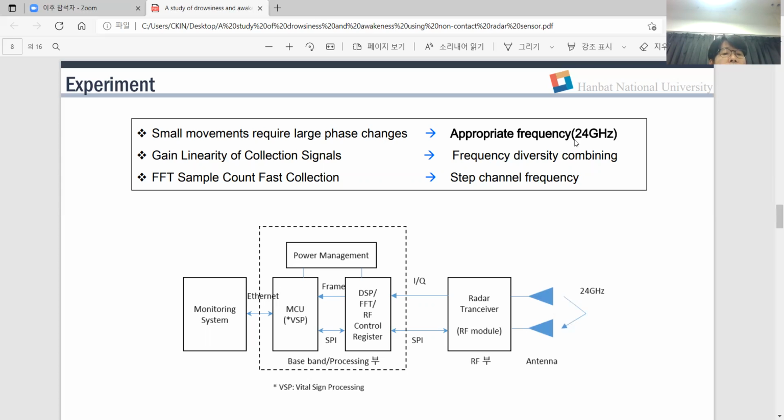However, since the human heart rate contains human body specificity and does not have complete periodicity, depending on the characteristics and conditions, there is a limitation in representing it as a single peak. Biosignal variation information, that is, variability with time, is an indicator according to the activation of the sympathetic and parasympathetic nervous system, and contains more human body information than the heart rate per minute. In order to use the signal acquired from the radar sensor at the same level as the ECG, it is necessary to process the output in the time domain to obtain biosignal characteristics.